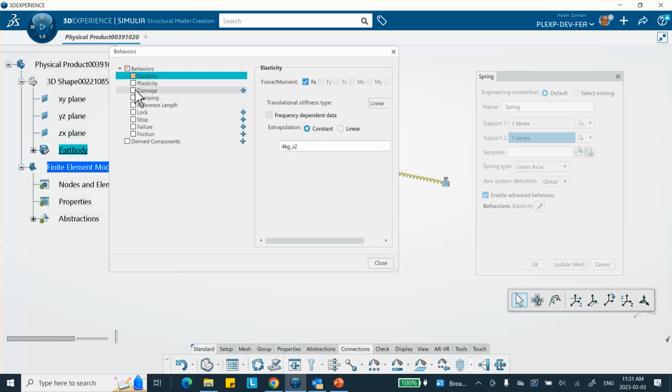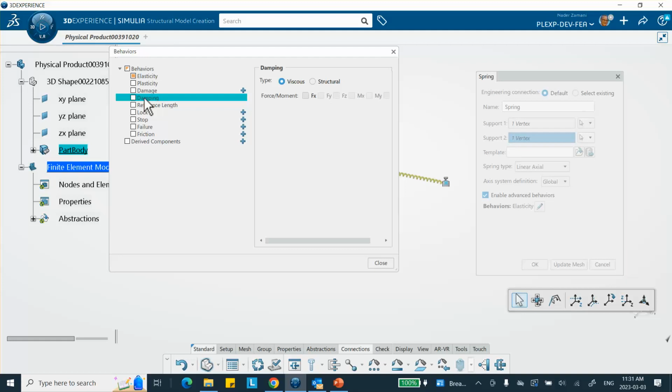Now, if you go and select the damping, nothing will happen except that you have to select the text. I suspect this is a bug that needs to be fixed, okay? Usually when you select on these boxes, this should light up, but it doesn't here. You select on the text there and you select FX because you have no other choice really.